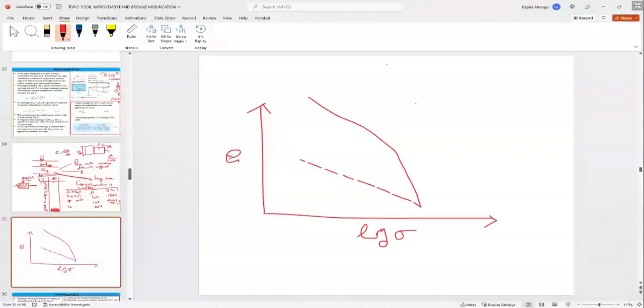Maybe no. Let me save the day. You know very well that you can determine the specific gravity of the soil particles, and then saturate the sample. When the sample is saturated, determine its water content. You know the saturation will be 100%, and you probably have determined the specific gravity.